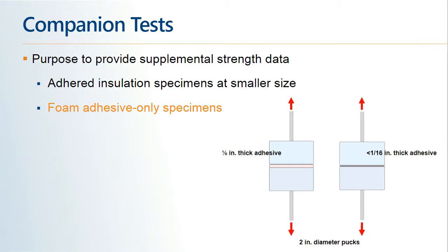One, we tested with a 1/8-inch separated gap space between the pucks, and we did that because we noticed when we fabricated the 4x4 samples, that when we applied the weighted buckets to the sample, we would end up with approximately 1/8-inch thick adhesive, flattened from the weight. And so we thought that would be good. So we devised a jig that would create a gap space between the pucks so that when we applied the adhesive, it would be representative of the actual 4-foot by 4-foot specimen.